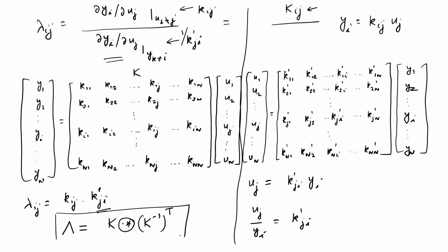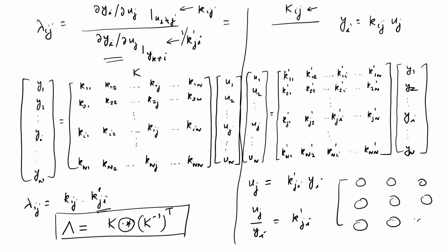And once you have the relative gain array, if it's a 3 by 3 system, the relative gain array will have 9 elements, and then what you do is you look for those elements that are closer to 1 and prefer those pairings. One of the properties of the relative gain is that the sum of the columns is 1. There are other properties, but it doesn't matter as long as you can calculate it. The pairings will become obvious when you look at the elements, so you just look for those elements that are closest to 1. Those are the pairings that have the least interaction.